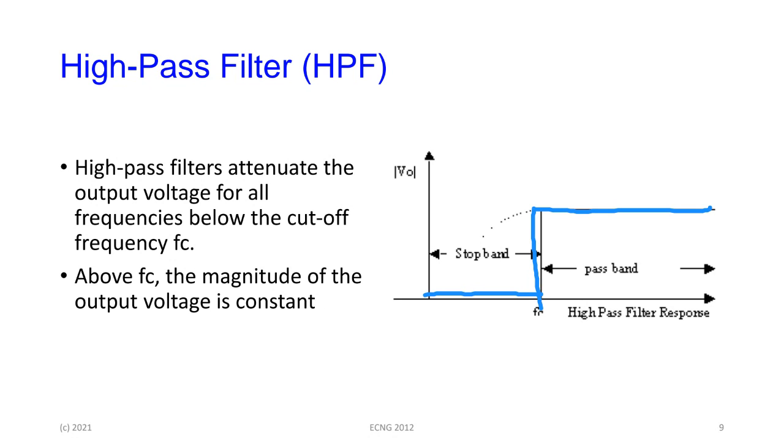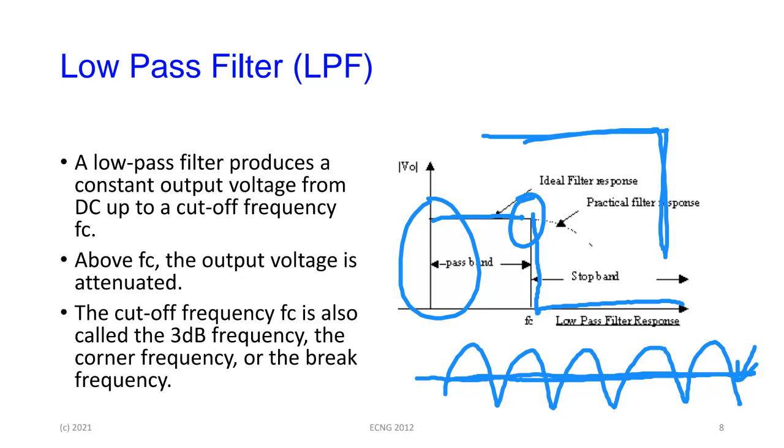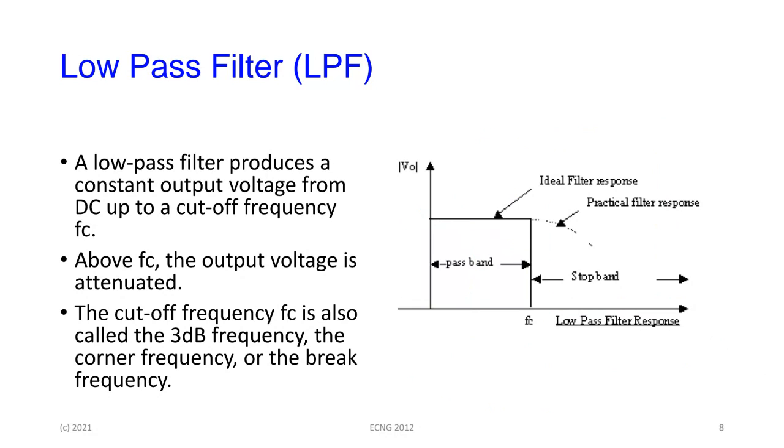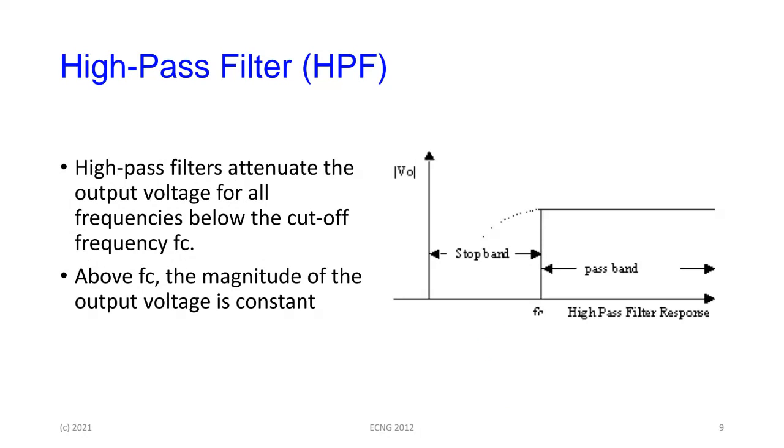So these sorts of filters you now see in certain types of communication work. You also see them in audio circuits, for instance. Like the low pass filter in an audio system, for those of you into loudspeakers and so on, would be the one that sends the low frequencies, or the bass frequencies. These are the ones that go to the large speakers, the big low frequency speakers that you have around. And then the other side would pass the high frequencies, which is what you sometimes call the treble frequencies, the middles or the mids or the trebles. And these go to the smaller speakers, like we mentioned last time, the piezoelectric speakers and so on. So an application of that is straight in the audio field.